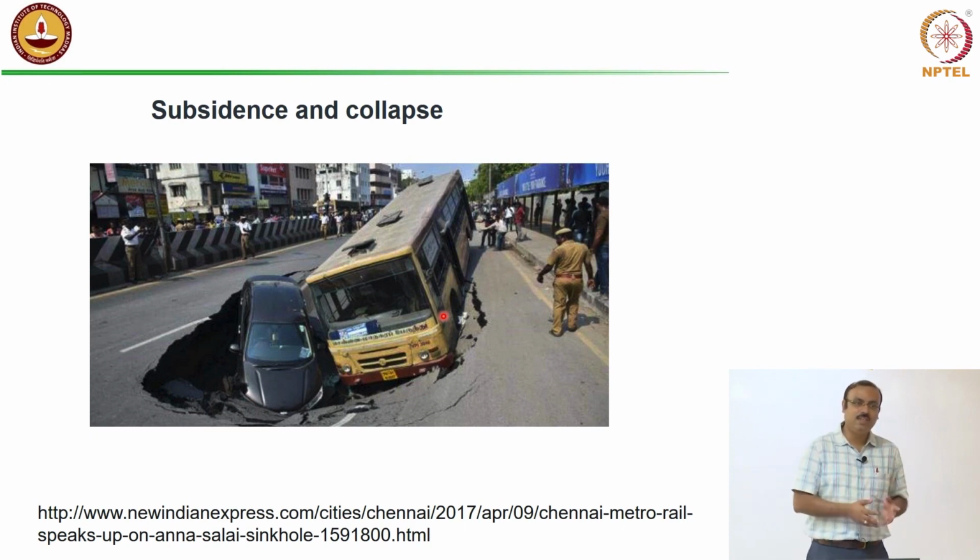So you have to design your tunneling methodology in a way that it will have minimal disturbance to the road on top. This is the real challenge, because the soil will be different in every part along the long stretch of the road. So you have to properly identify the soil, what type of soil you are digging, and what kind of precaution you are taking. Continuous monitoring is the key issue here.